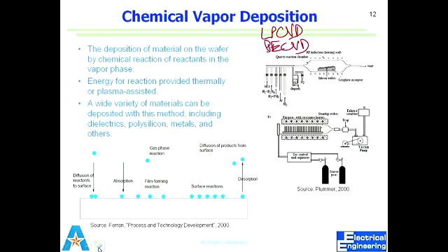So during the process, we have to keep an eye on the plasma. How do we make sure the plasma is on and maintained? Have you guys seen plasma? Have you guys seen Back to the Future? It's a very old movie. How do we see plasma? What do we see with plasma? Lightning. Glow. We see glow, right? So that glow tells us that, so there are eyepieces where you can see there is an indigo type of glow in there. So for RIE, for CVD, PECVD, plasma is maintained, and we have to keep an eye on the power supply as well as the chamber itself.